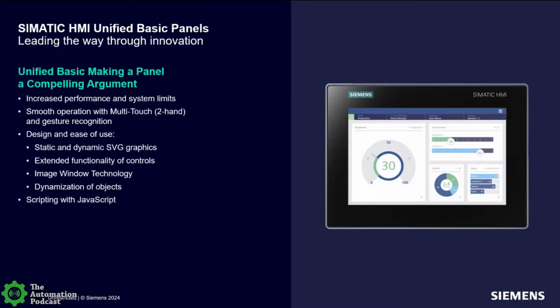We have adopted the same image window technology that we had in the other unified systems, which is, it's no longer a flat screen. If you've got a series of buttons that you navigate with at the bottom of your screen, in the past, every screen in your project would have to have those navigation buttons. And if you ever changed the path of one of those buttons, you had to do it to all of the instances in your project. With the window imaging technology, we actually can just separate out those buttons to a separate window and you leave them alone. It's sort of like a footer window or a header bar. You engineer that once and you manage it once. And then you're only changing the pieces of the screen that you really need to change for the operator to get the data they need to get.